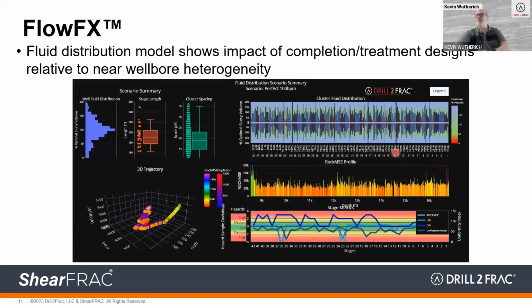So the next step that we do here is we want to try to predict how our completion design is going to look. We can do that through a number of different methods, but we built this model called FlowFX that looks at the real-time rock properties in the near wellbore that we get from drilling data. And we also look at the completion design. We look at your number of clusters, number of perf per cluster, hole diameter. We look at how they relate relative to stress shadowing, perf erosion, and all that sort of stuff.